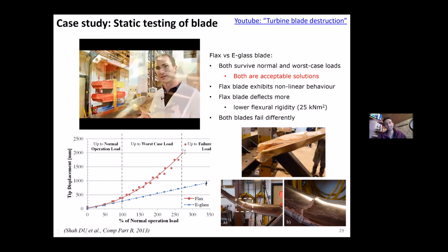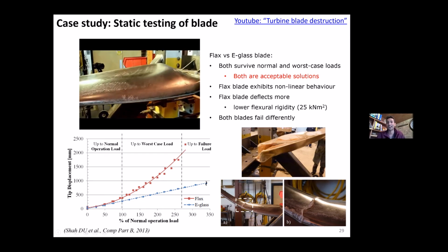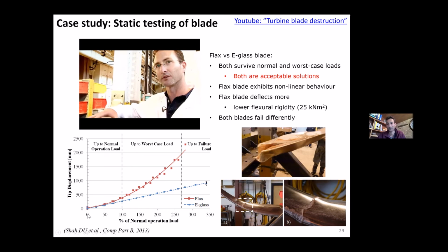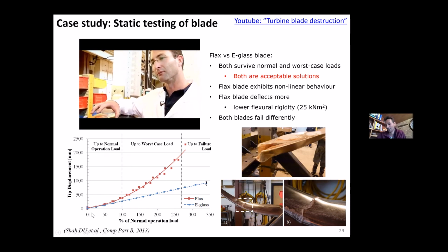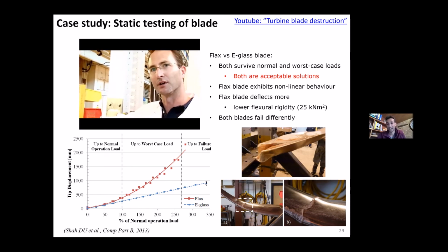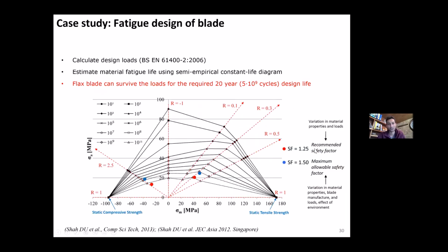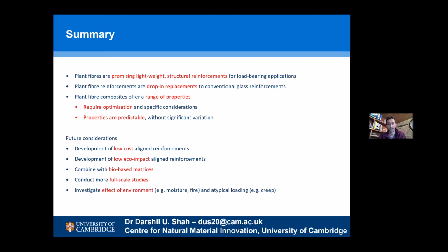That it's passed in terms of strength, but not necessarily in terms of stiffness. Something interesting also was the nonlinear response, which the standards do not consider based on synthetic materials that we typically use. We did some fatigue analysis, and it was quite apparent that fatigue was not a problem for these natural fiber composites, and we would quite easily surpass the 20-year design life in terms of fatigue.